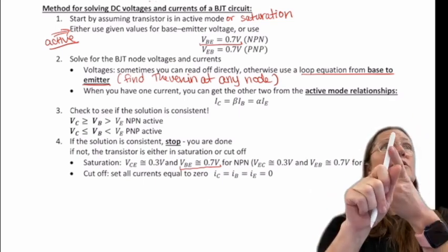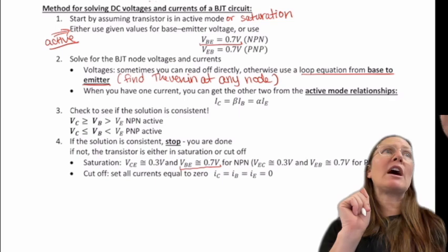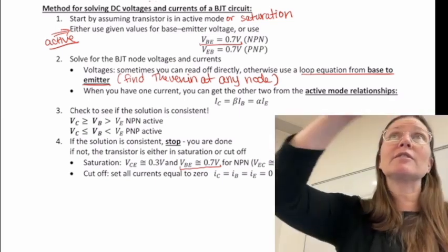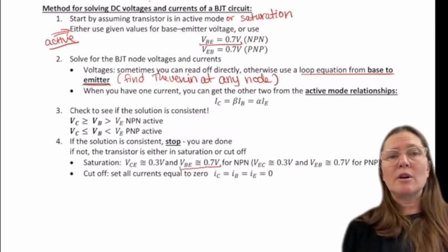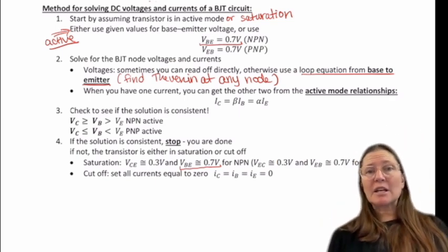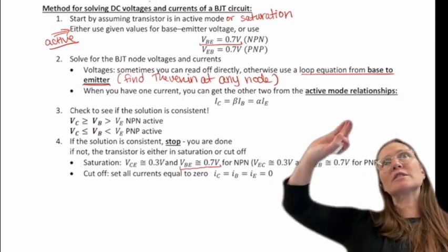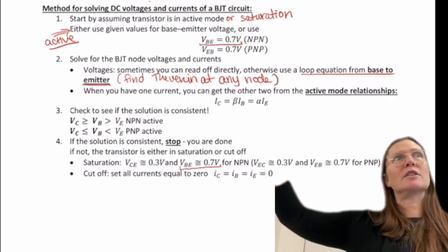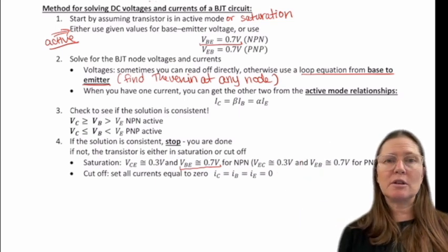So you would find the resistance of it and the voltage of it. And then you would use that as the base circuitry, and then it becomes much simpler. Same thing could be happening at any of the other nodes too. You may have a more complicated circuit, so you disconnect it from whatever it's on to the transistor and then find the Thevenin of that portion.